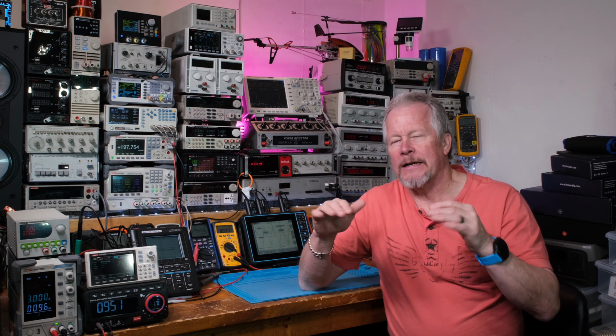By the way, before you send these off to a board house, you would probably look at each layer and make sure it's what you want, because sometimes you're so zoomed in on the screen that you might miss something. Once you print out or zoom away and look at the Gerber files and each layer, all of a sudden you realize, oh, my silk screen is on top of something else, or there's something you're going to find usually.